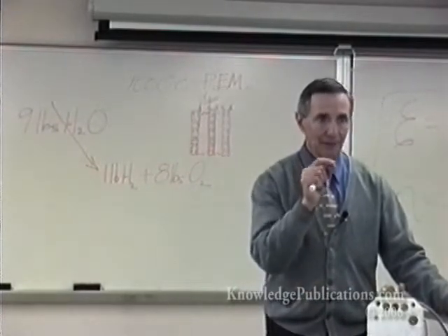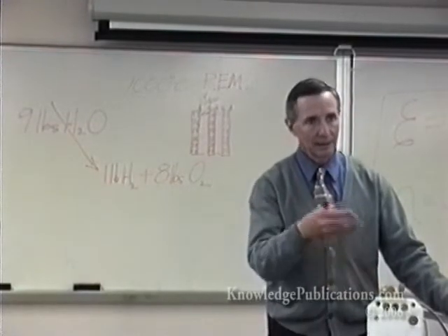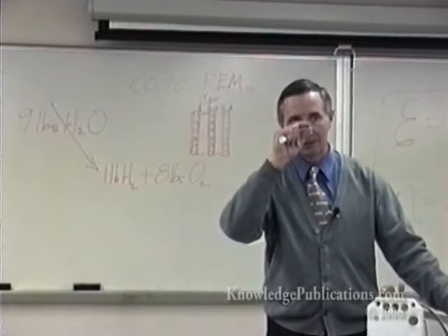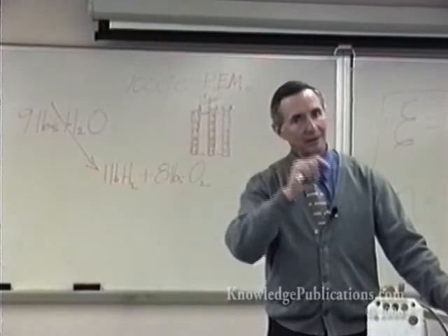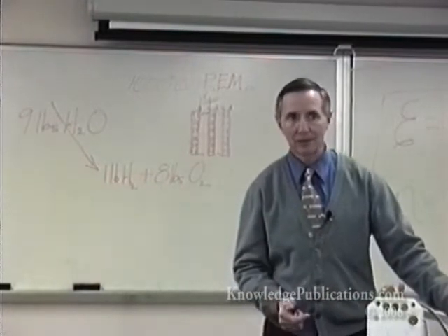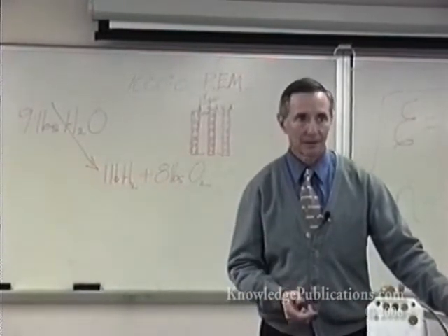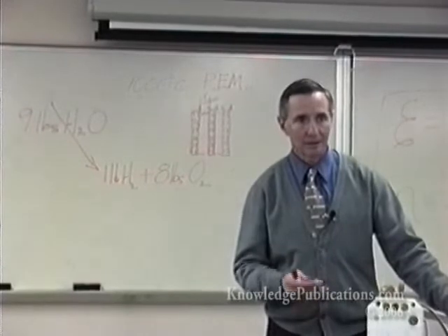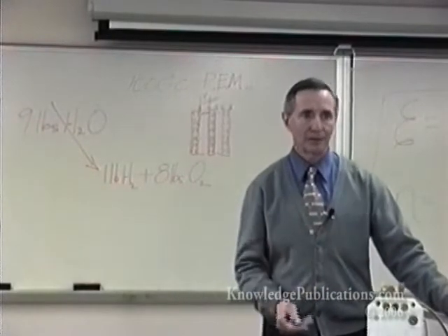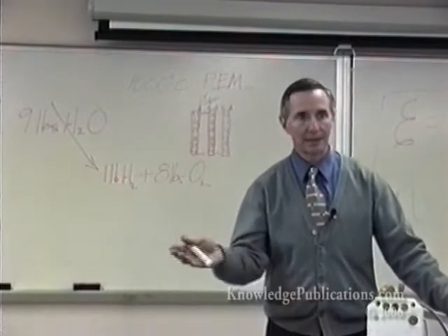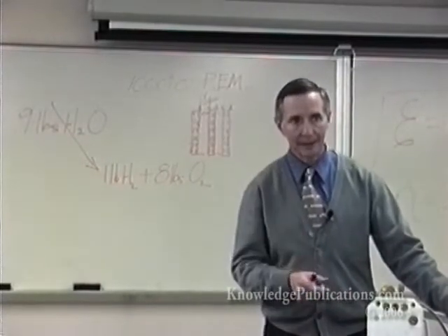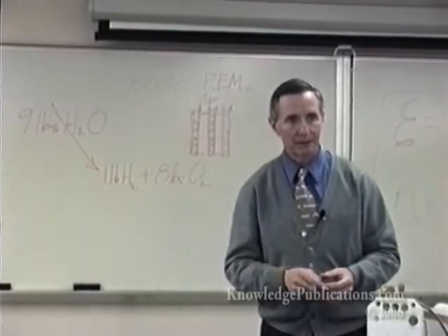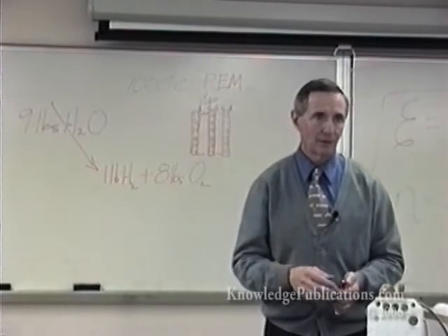But the rate at which that MEV shifts unwanted things in the air to acceptable things is minuscule compared to putting hydrogen in a piston engine. There's hardly any approach that cleans the air faster than putting hydrogen in a piston engine, just with ambient air. Sure. Engines breathe a lot of air. They bring the temperature to a very high peak instantaneous temperature at which the reactions proceed very rapidly, much more rapidly than you can get on the radiator or the muffler of a car.